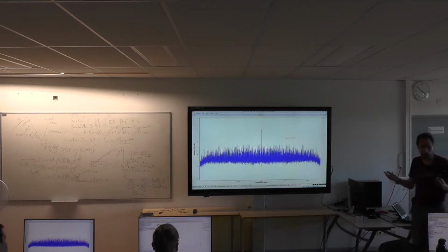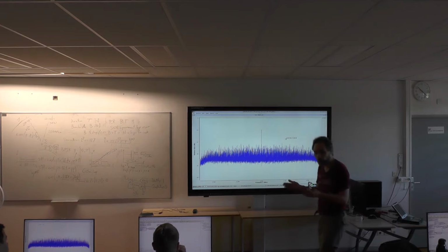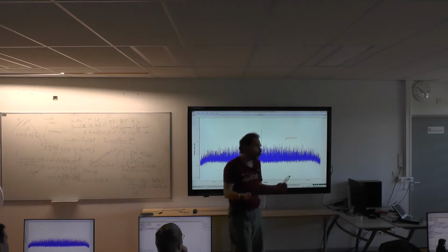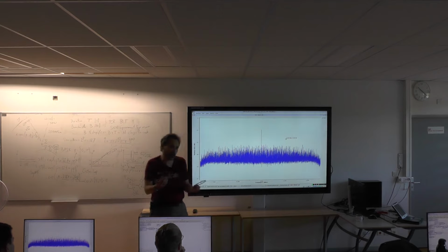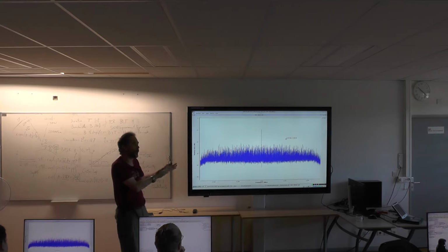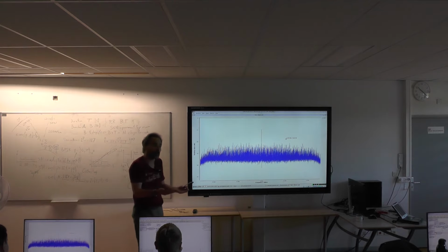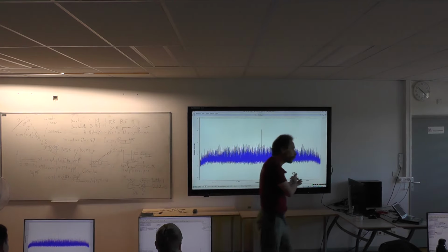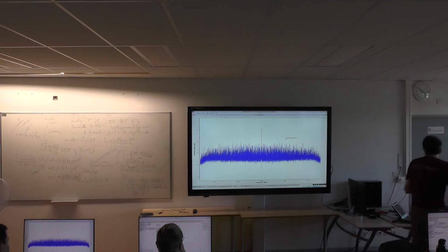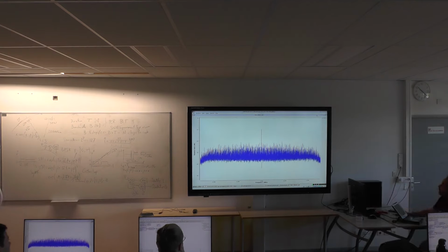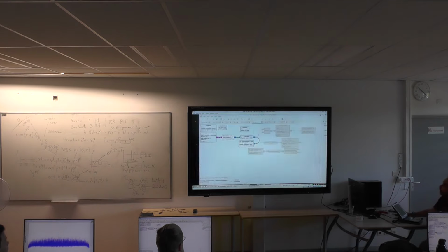But you might wonder, I'm bothering you for an hour and a half with processing GPS signal. You're not really sure if you understand the processing. And then you're not really sure if I collected data correctly. Did I forget to power the antenna? Did I forget to actually connect the antenna? Is it even worth finishing this lab session and checking if there is some GPS signal in there? What we just said is if we square the signal, we should cancel the phase.